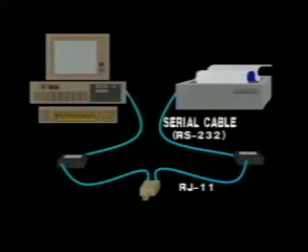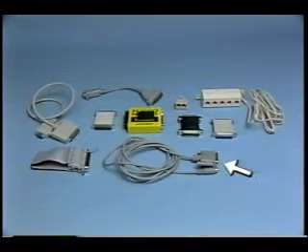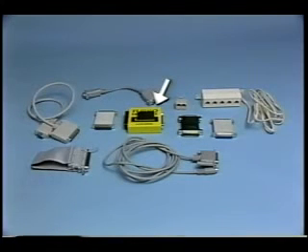StarBus simply combines all of the data conversations onto one telephone wire pair and routes the appropriate data to the proper intercom station. On all installations, it's best to bring a handful of gender changers, two-way splitters, 9 to 25 pin converters, Apple Mac cables, and a serial to parallel converter.